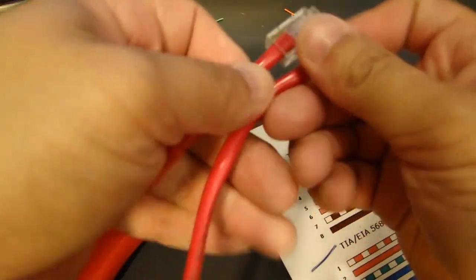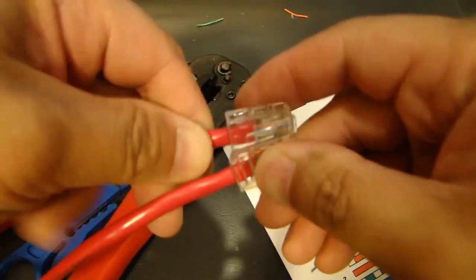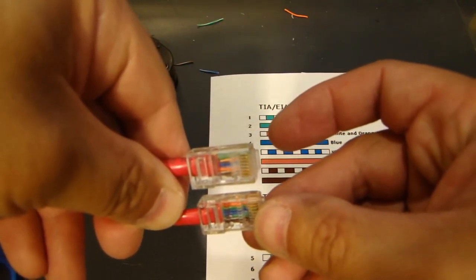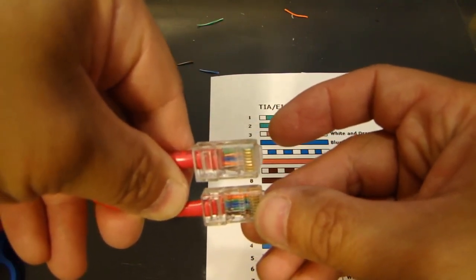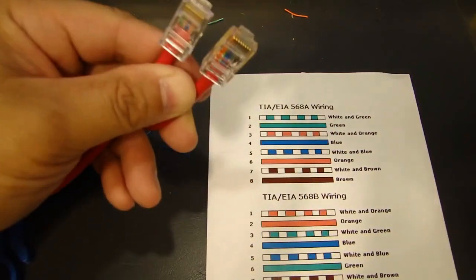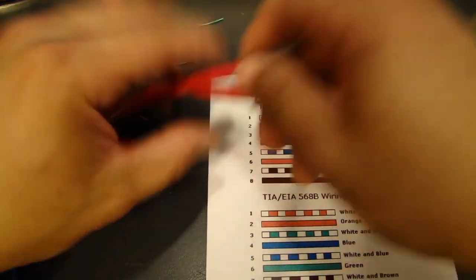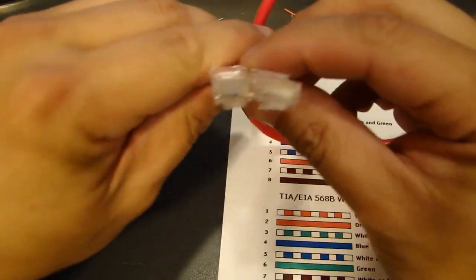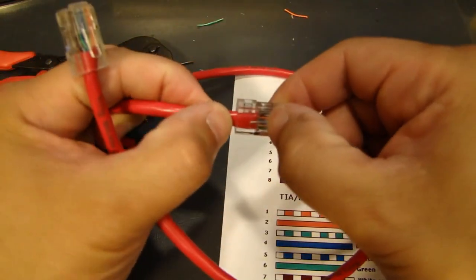So there you go. If I put this end to end, you'll see that the top one starts with the white, green, green, and the bottom one starts with the white, orange, orange. So this makes it a crossover cable. Now a couple of things I want to point out. After you crimp it, you should do an inspection on it. Again, one is that the